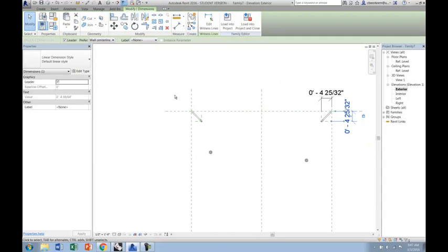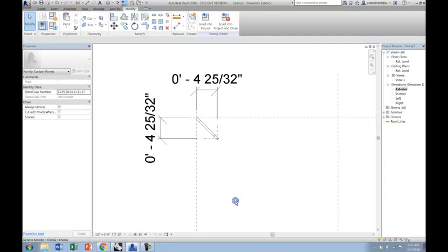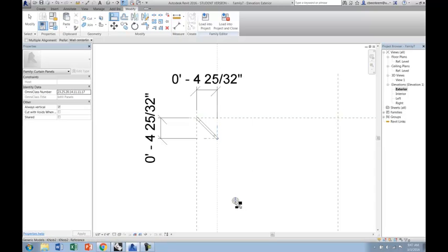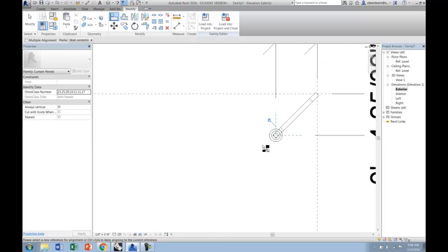Where did I lock that one? Yep. Last two. Okay, so now I can select the knob and do an align in plan. So that reference now goes, and those little blue reference lines that I'm getting are those strong reference planes that we turned on. So if you're not getting these lines to show up on this, you need to go back to the knob and make sure that your reference planes are turned to strong in order to get them correct. We'll just go around and snap the knob, make sure I'm hitting the lock. This reference plane, that one.